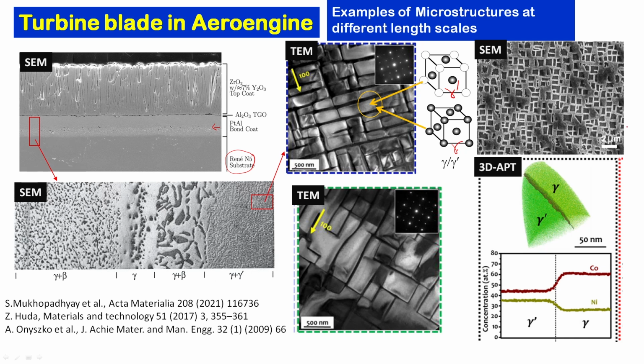And if you look at the structure under a scanning electron microscope, it will also look like a checkerboard, but look at the dimensions and the features, they are different. If you magnify this structure, it will look like this, you can see big blobs like checkerboard structures. The majority are gamma prime, these big blobs, and these black areas which are marked here are gamma. Between gamma and gamma prime, there is a very nice microstructural coherency, and that is why gamma will never grow, gamma prime will never grow, they will remain the same size, and that is why this is a wonderful material. And in order to stop the growth of gamma prime at high temperature, we have to add so many elements.